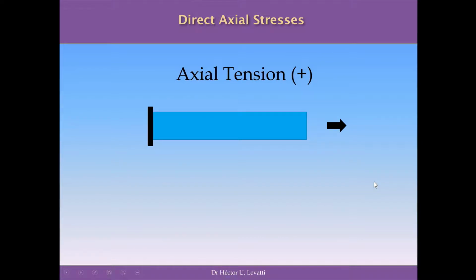When we apply an axial force on a structure, let's say, for example, we have this beam in here, which is fixed to the left side and free to the right side, and we apply a force to the right extreme, we're going to deform this structure, and we're going to produce this reaction in red in here with the opposite direction to keep this structure in equilibrium.